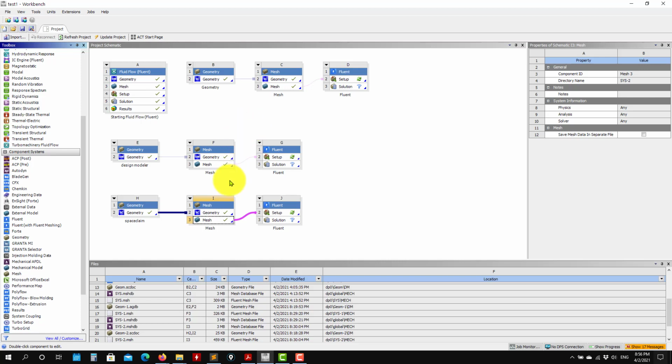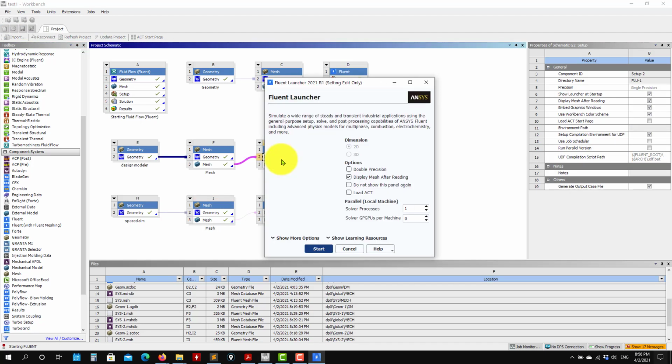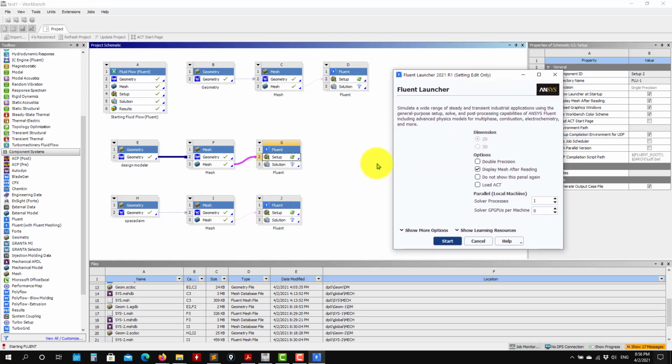The only thing you need is to fetch the mesh, whatever you put in this folder. So in my case, I will open this one. It doesn't matter. Remember, when you click here, Fluent will open automatically and recognize the meshes, 2D or 3D. Here always choose double precision, and for the number of processors I will put 4, and that's all. You don't need to set up anything else. You don't need to give the path, nothing, okay? Workbench knows where all the files are located.